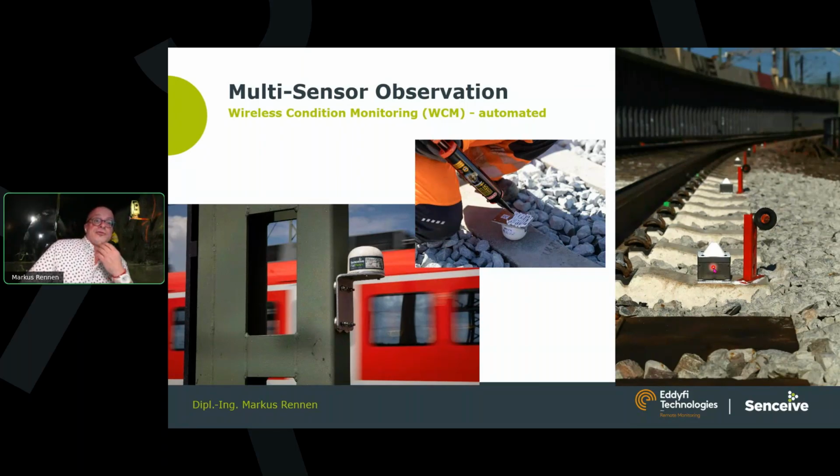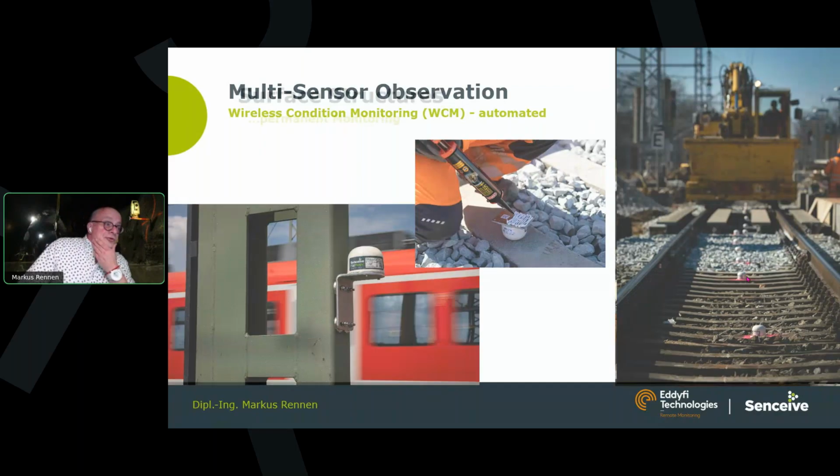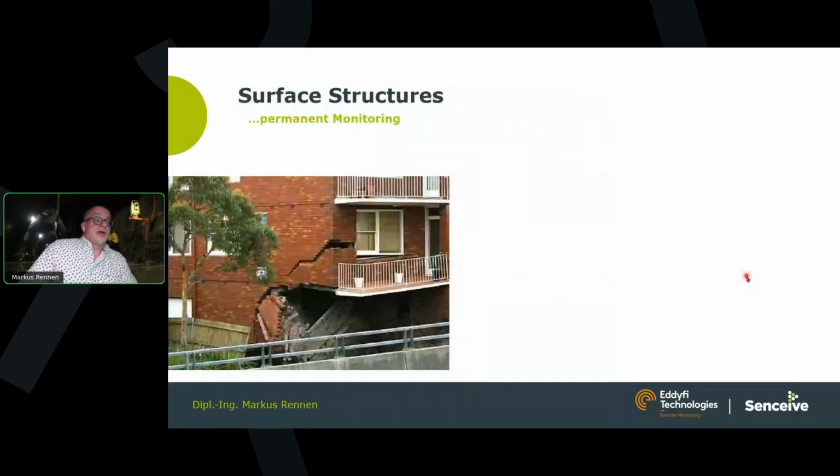The nodes are glued to the rail track, which of course applies similarly to other construction measures, gluing or screwing them to a wall, where they provide relative movements, like here, for example, in a consecutive line of observations, providing cant, twist, versine measurements, or even, on an acceptable accuracy level, vertical displacement. Well, that refers also to infrastructure and buildings above.